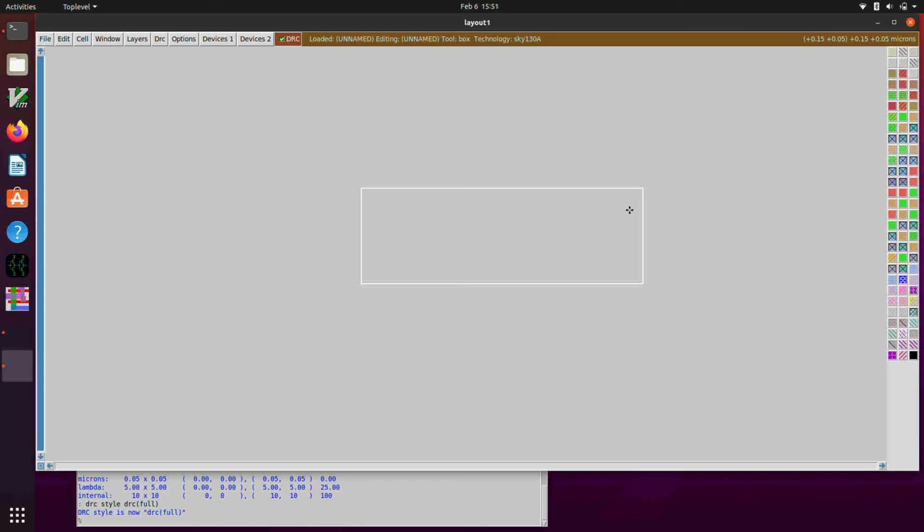And until you get used to the design rules and while you're doing a small cell layout, it's best to have all the design rules enabled. Magic does something called incremental design rule checking, which is really, really great. It'll show us design rule violations as we draw a layout interactively, and then when the design rule violations disappear, the little white dots that appear to show a design rule violation also disappear. That's really, really, really handy.